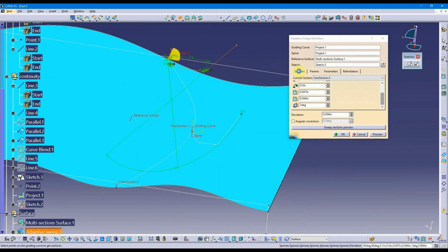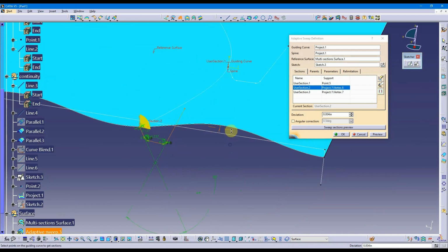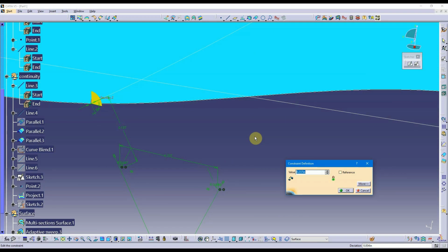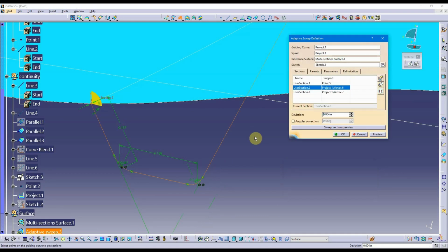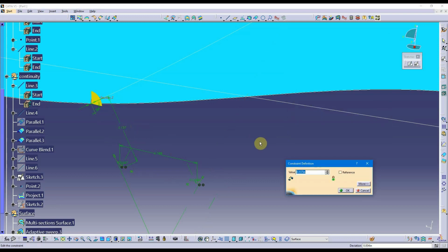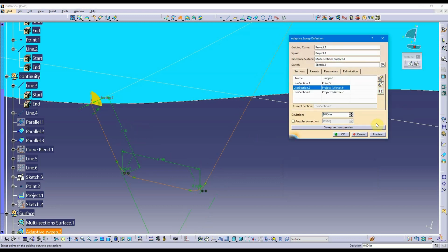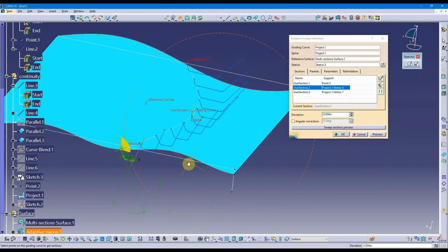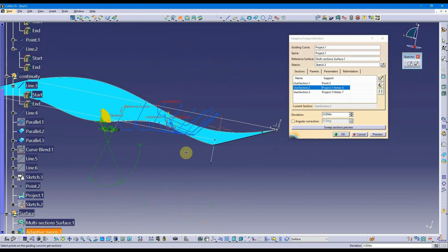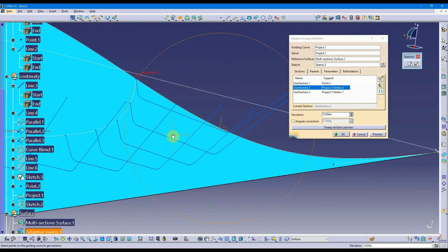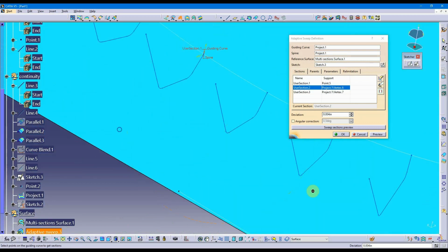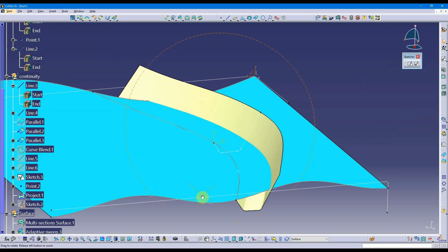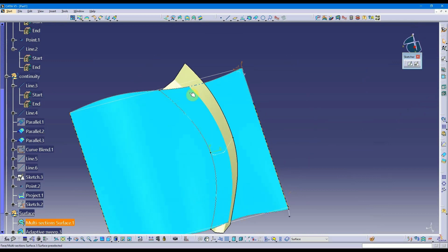And then let's go to the second section. I want to make this one slightly smaller, so I can come in here and do 0.1875, and then let's make it slightly deeper. And I can do a section preview here, and it will show you what all the interpolated sections will look like as it sweeps through. You can see right here, let me just hit OK. You can see my sweep as it goes through. So it gets wider as it gets down to this end.